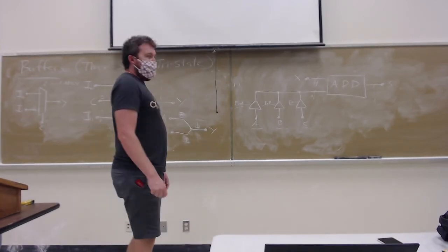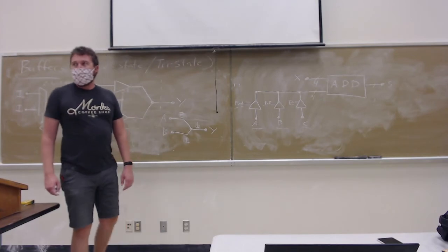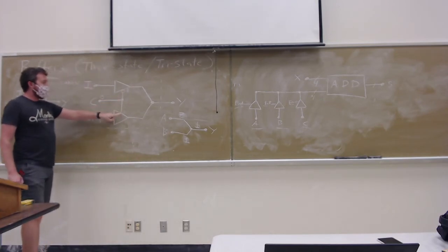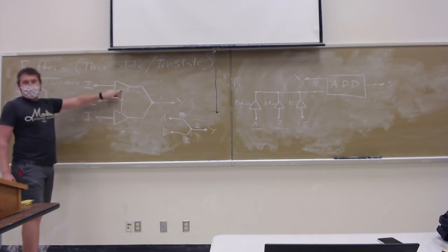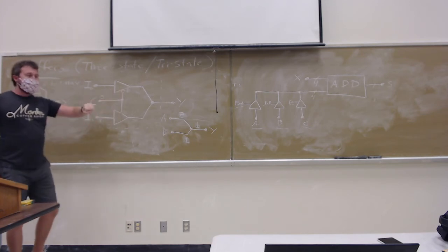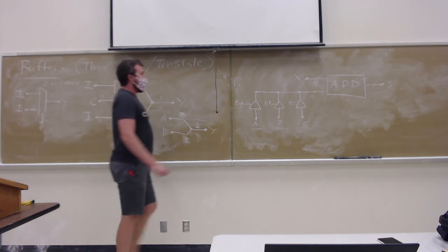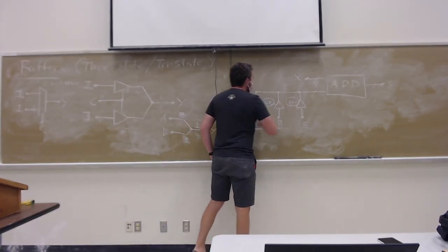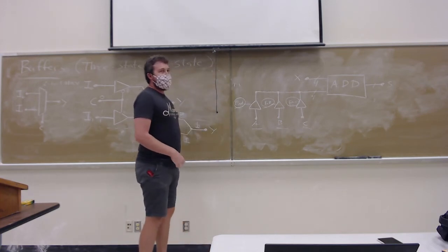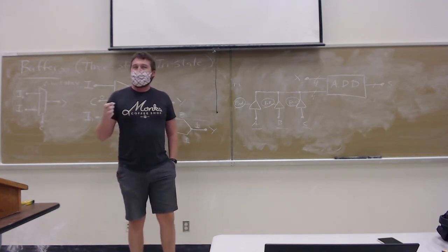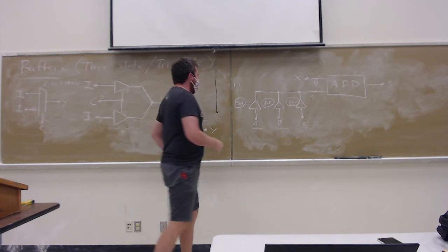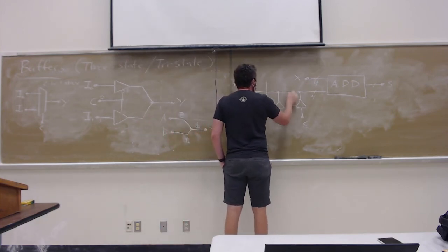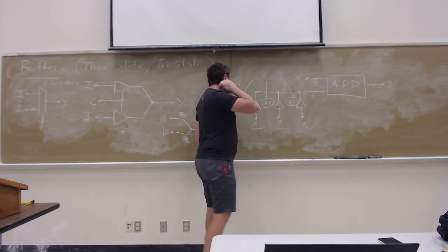Now there's going to be a problem with this, right? Here we had it locked in, right? C was directly tied to this as 1 and this is 0. And so we knew that we were always going to have one or the other, right? But if we set up a circuit like this, with these multiple enable signals all attached to the same thing, we need some way of making sure that only one of these is 1 at any given time.